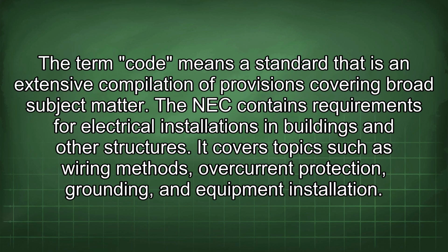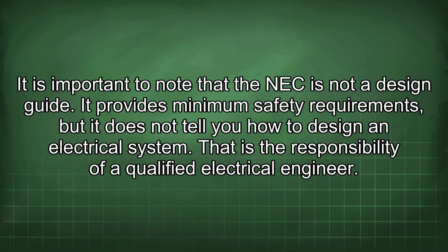The term code means a standard that is an extensive compilation of provisions covering broad subject matter. The NEC contains requirements for electrical installations in buildings and other structures. It covers topics such as wiring methods, overcurrent protection, grounding, and equipment installation. It is important to note that the NEC is not a design guide. It provides minimum safety requirements, but it does not tell you how to design an electrical system. That is the responsibility of a qualified electrical engineer.